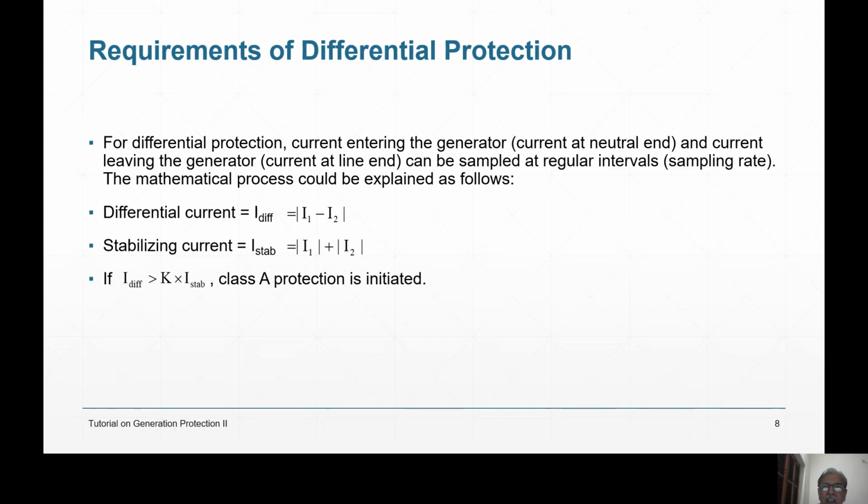Two CT points at one side were shorted. The terminal block was burned, and therefore one side CTs were shorted. Second side CTs were then obviously feeding the relay. So it was not an internal fault. Terminal block burned.